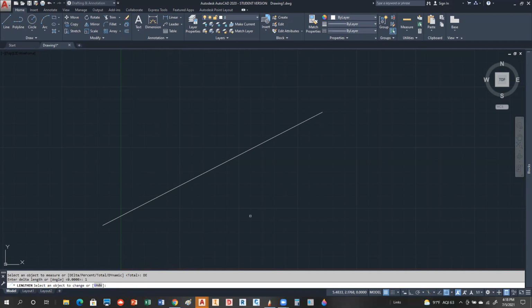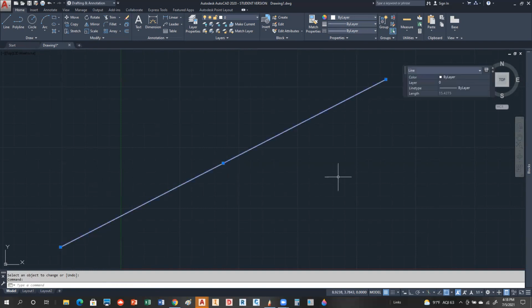The side that you touch on is the side that it's going to add to. So notice if I click it here, I add it. There's one. There's another. There's another. Now it's really not adding it, it's actually just pushing the endpoint out. So if I come back and do it to the other side, and when I get out of this command and click on it, notice you just have grip, grip, and grip. So it didn't actually add pieces, it just moved that distance out.